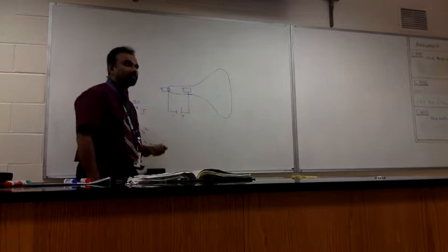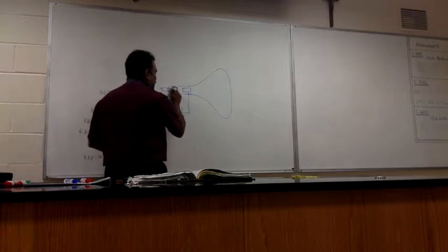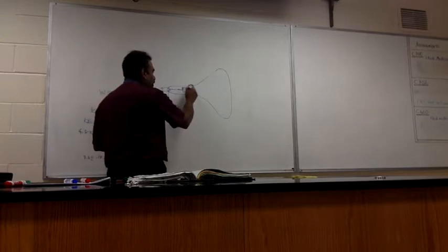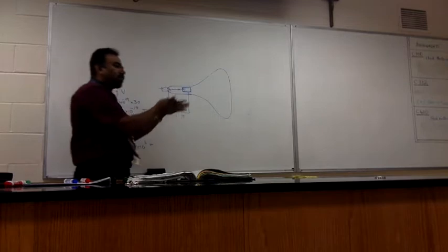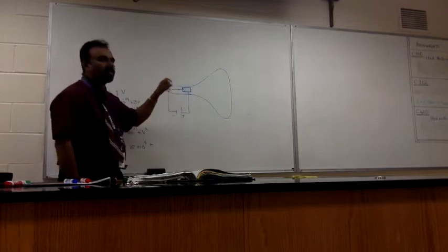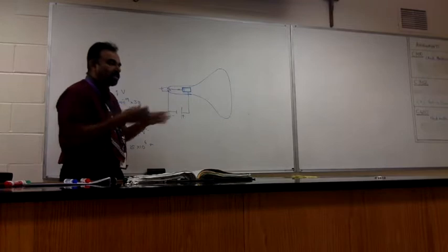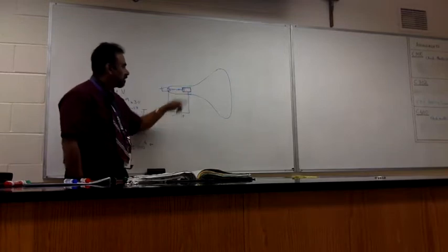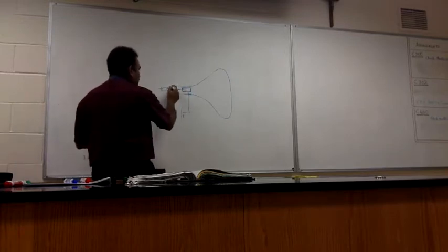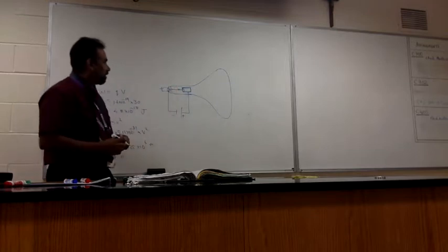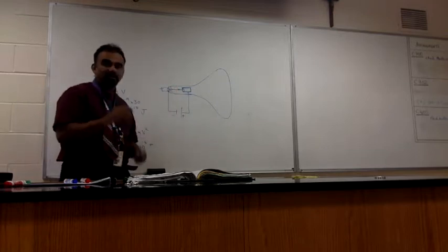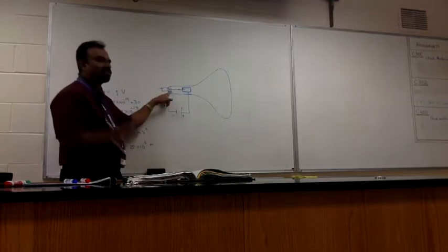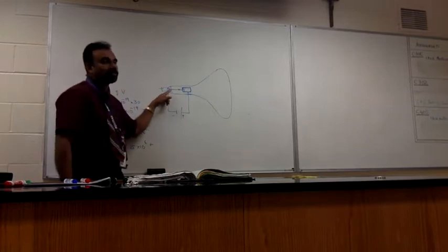So when the electron comes out from here, it gets accelerated and goes through the middle of the cylindrical anode. It's actually focused through the middle. There's a different focusing mechanism that makes it go through a certain region. Before it goes further, there are some grids over here. The grids are used for brightness control. Have you changed the brightness of a television? What you're doing by changing the brightness is trying to limit the number of electrons going across. So we have brightness controls and other controls like that.